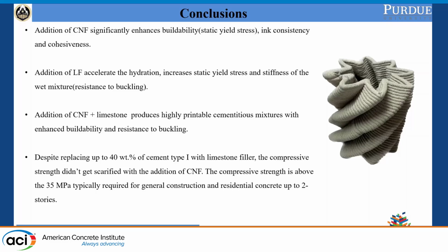The future work remains in the durability properties, because by replacing the cement with limestone filler, we are interested in durability. However, there are already a few studies showing that a small amount of CNF fiber can improve the durability performance significantly, so it can also offset some of the dilution effect to some extent. And we will also study the real mechanism of the interaction between the CNF, cement and limestone.